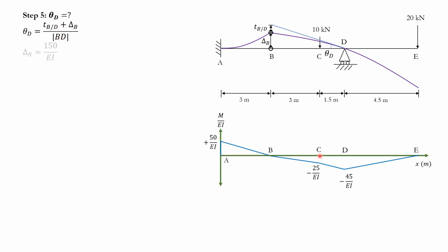So I'm going to go to my diagram. Delta B is known, of course. This will be the second moment-area theorem. So it'll be the moment of areas about which point? The first letter, point B. About point B, these are the areas of concern: 1, 2, 3. Why do I separate them like that? Because it's easier to find the centroid for a triangle and a rectangle separately rather than for a whole trapezoid, that's all.